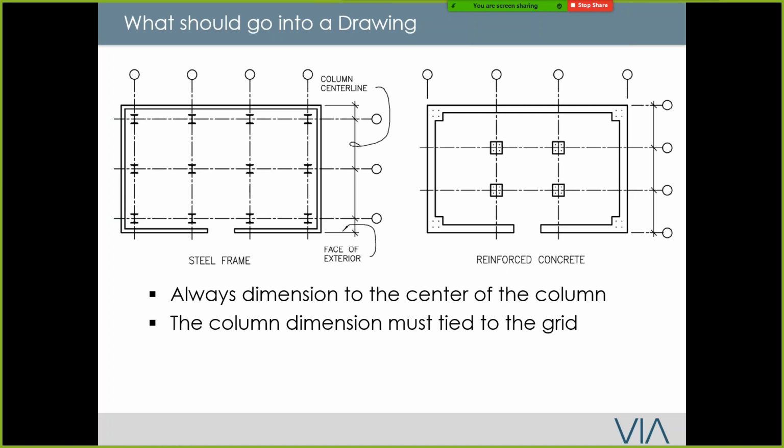So here it's just another convention. If you're doing a steel building or any other building, you always dimension it to the center. Reinforced concrete, yeah, it basically shows you, okay, steel frame, this is how we do it, and reinforced concrete, same idea.